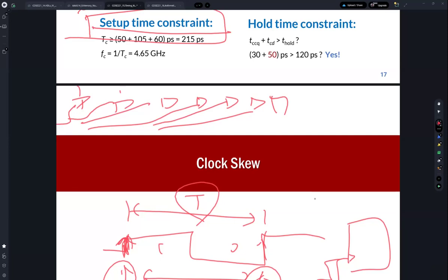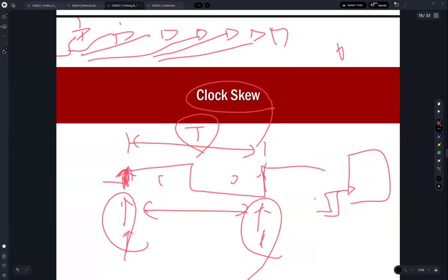Okay, that is the ideal clock signal, but this timing can be different because of wire delays. Okay, so this difference of clock edge timing is called clock skew. Skew means that the timing of the real clock can have some changes. So when we analyze the timing constraint of the system, we also need to consider clock skew. So that is the real changed timing of the clock rising edge. Okay, so it's a clock skew.